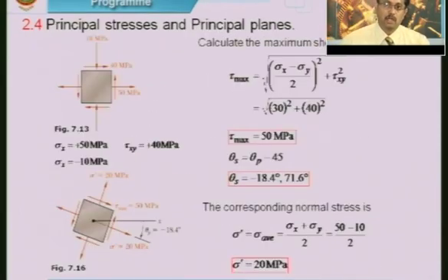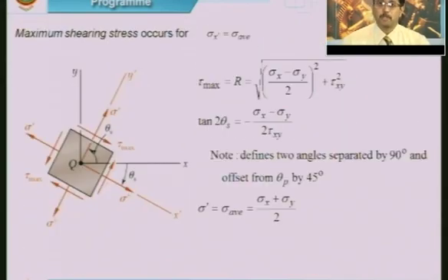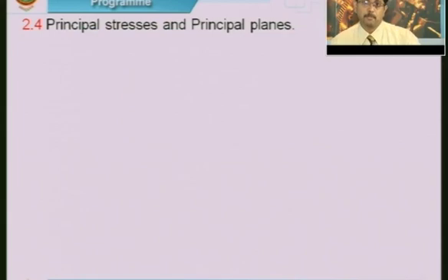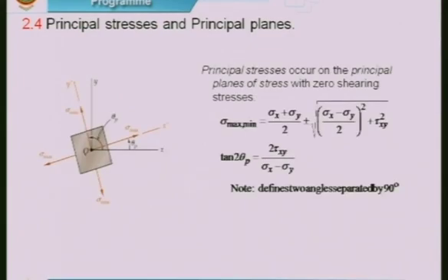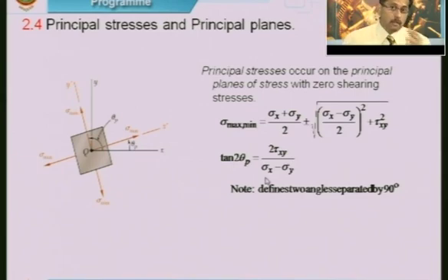We have looked at how to derive the expression for principal stresses and principal strain from the previous class, where we had the normal stress equation. From that we derived the principal stress formula, which is given by this equation for the maximum and the minimum, which differ by plus or minus this value. The plane on which it acts is given by tan 2 theta p equals this. Then the inclination of the principal plane and the normal stresses acting on this plane is indicated as this.